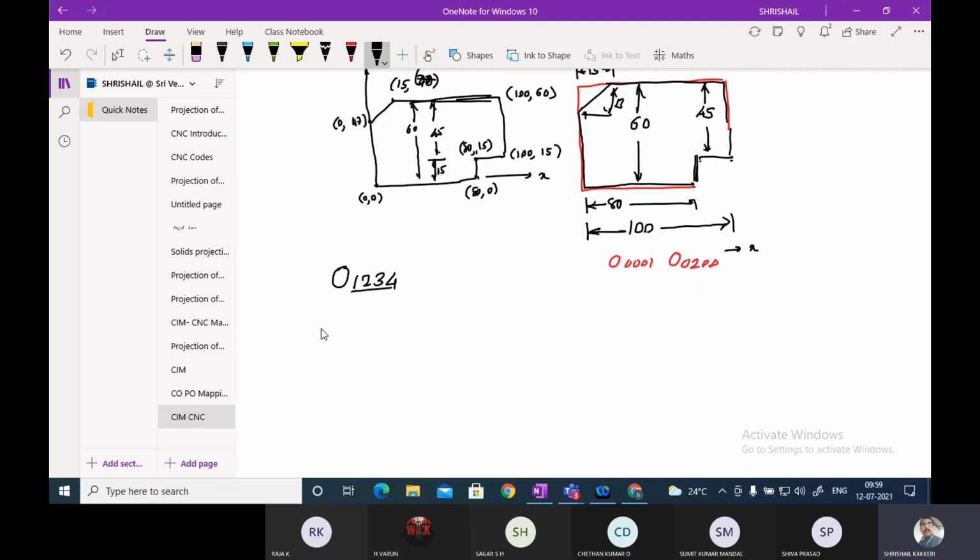Now in the beginning I will be taking the program number, G0001. Or G123 also can be written, no problem. One can write N1, N01. It is the program statement number. N is that particular line, called by N01, but it should not be repeated anywhere. If I write N01, that will take this only. Only one time it should be written.